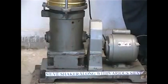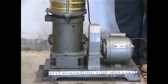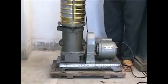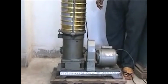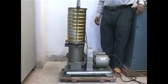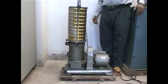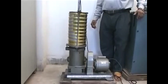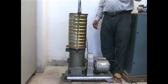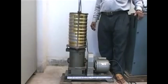Now you see that we have put the sieve set, on which we took 500 grams of soil sample, on the mechanical shaker, and we are going to subject it to mechanical shaking for about 10 minutes. After that we are going to find out the weight of soil retained on each individual sieve, and from that construct the grain size distribution curve. So we'll start the shaking now. You just watch it, and then we are going to come back to it.